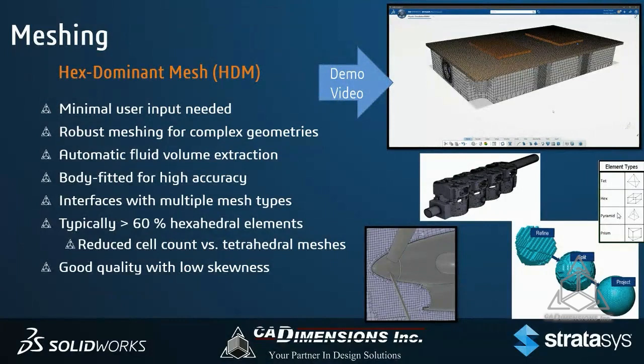We've got multiple physics going on. We've got different flow domains. We've got solid physics. We've got conduction. We've got convection. We might have radiation depending on what we set up in this analysis. So we've got a ton of information, but we can break it down almost component by component or domain by domain and grab our mesh very, very quickly, especially with simple geometry like those chips in that board.